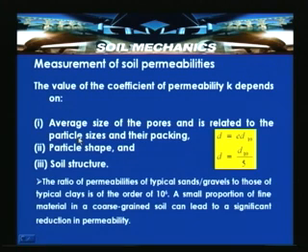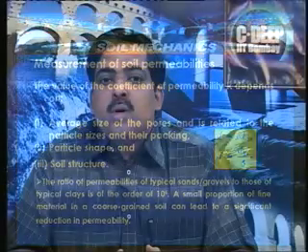So, we have discussed earlier that particles with a rounded arrangement can have large pore spaces. So, in those cases the permeability can be high. For example, if the particles are subrounded or angular in shape, then the flow can be affected because of the interaction of the water when it is flowing through those pore channels, passing through particles having angular shape.